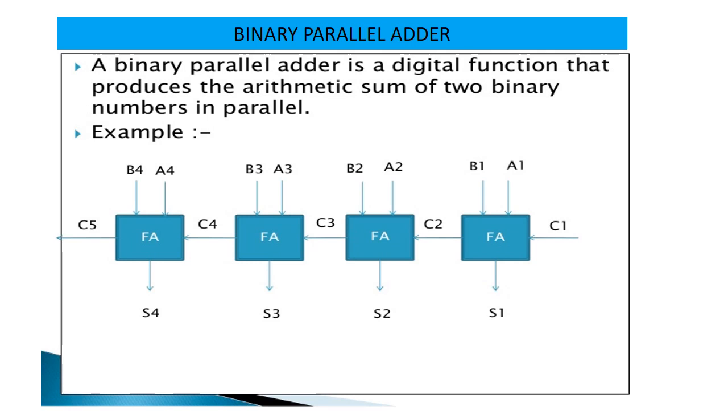The figure shows the interconnection of four full adder circuits (FAs) to provide a 4-bit parallel adder. The augend bits of A and addend bits of B are designated by the subscript numbers from right to left, with subscript 1 denoting the lower order bit. The carries are connected in a chain through the full adders. The input carry to the adder is Cin and the output carry is C4. The S output generates the required sum bits.